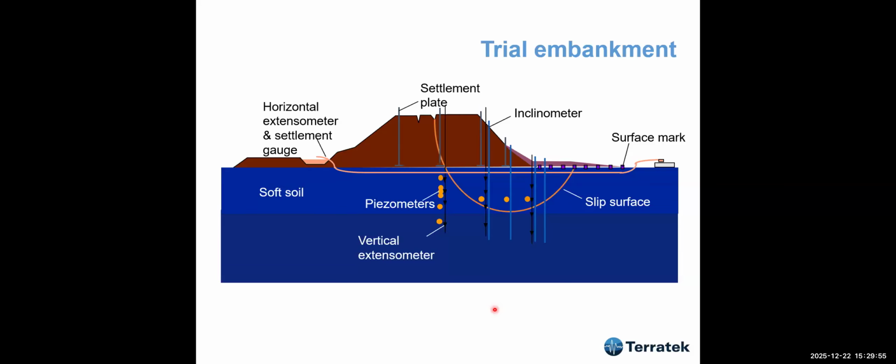So we installed it. The embankment was fully instrumented, and we had lots of inclinometers, piezometers, and horizontal extensometers. Also, we had a vertical magnetic extensometer as well. So lots of instruments, and it was a